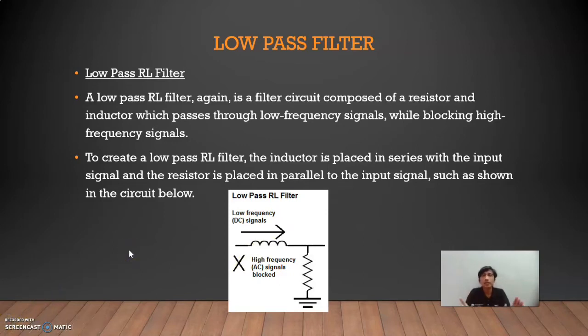How it works is based on the principle of inductive reactance. Inductive reactance is how the impedance or resistance of the inductor changes based on the frequency of the signal passing through the inductor. Unlike a resistor, which is a non-reactive device, an inductor offers differing impedance values to signals of differing frequency, just as a capacitor does.